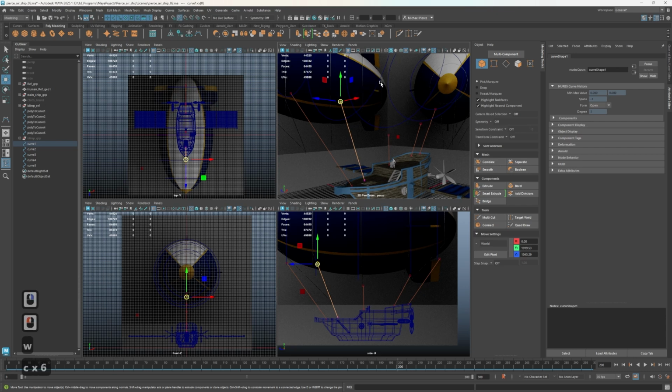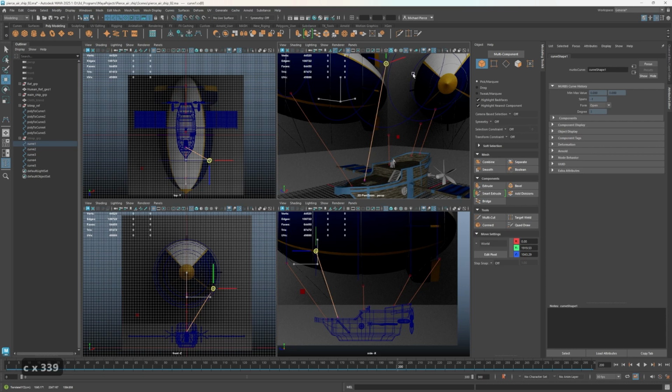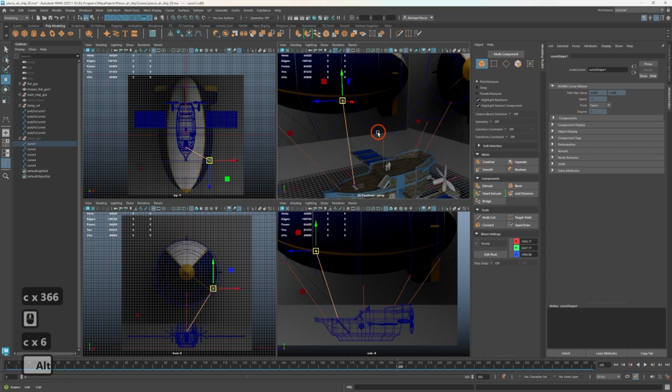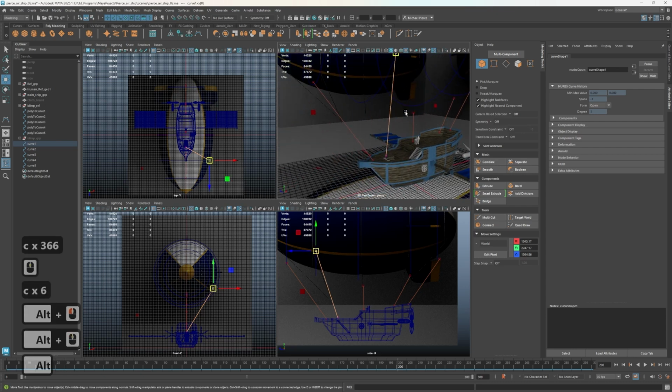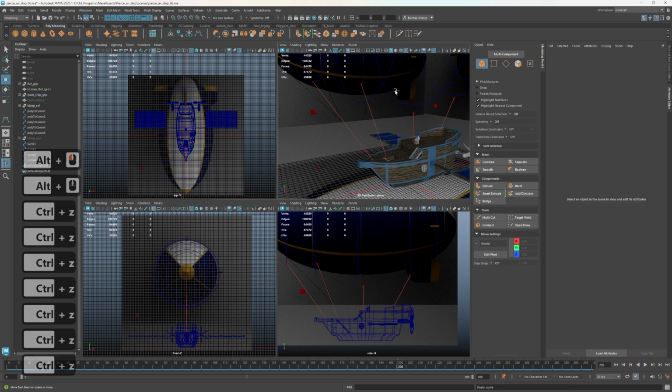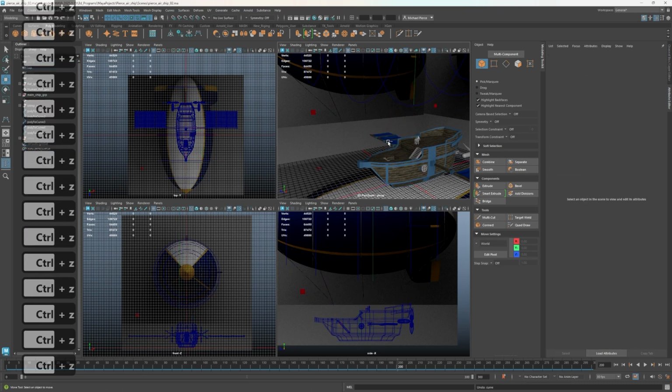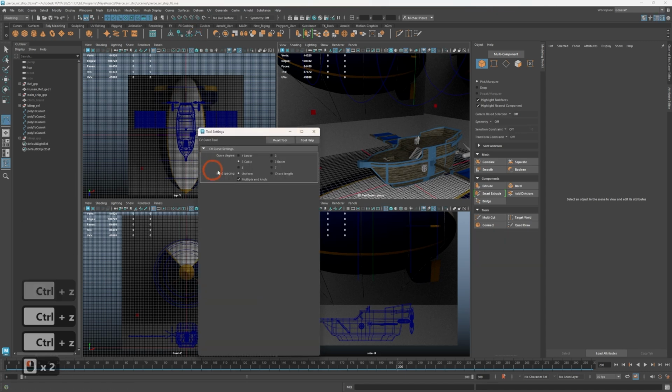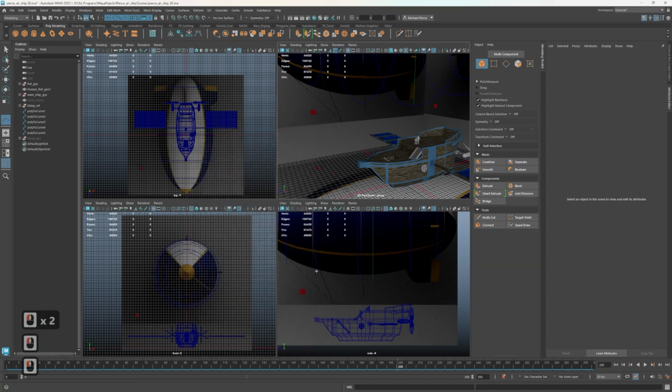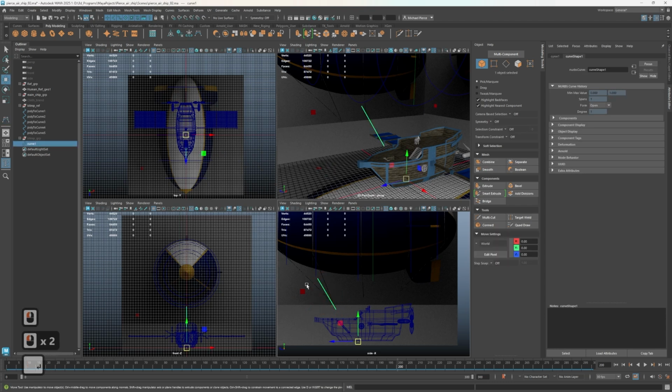Now, I'm going to hold down the C key, and then I'm going to use holding down C and the middle mouse button as a button and drag this along. Now, ideally, you'd probably want it close to here to be out, right? You know what? I'm going to undo these because they don't look like proper curves. Actually, I'm just going to double click on this and do linear instead of cubic. That's probably why. So if I now hit 1, 2, and hit enter, there we go.